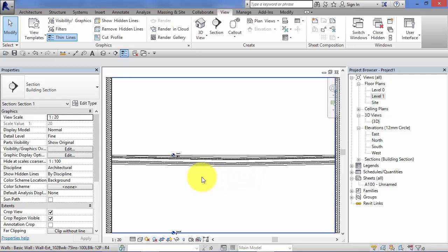That's not a problem. We can actually set one of the layers in our floor type to have a variable thickness, and if we do so, that slope will be taken up just by that layer only, and I'll show you how to do that later on in this unit.